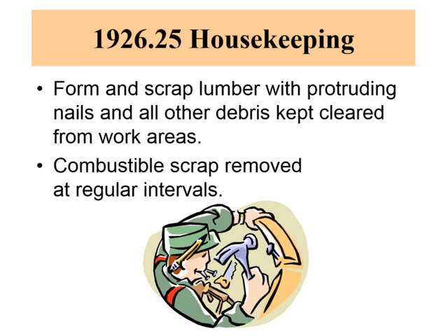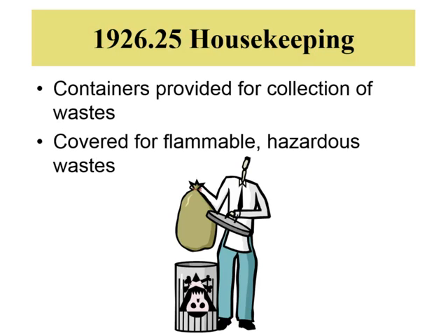And then housekeeping. To me, housekeeping is probably the biggest challenge in construction work. Everything we do, we're developing some sort of scrap and waste, etc. We want to make sure that that's taken care of. Combustible scrap needs to be removed at regular intervals to make sure we prevent fires. Make sure that shooting nails are taken care of. Anybody that stepped on a nail knows how uncomfortable that can be. And then making sure there's containers provided for collection of waste, and if it's flammable or hazardous waste, that it's covered up.